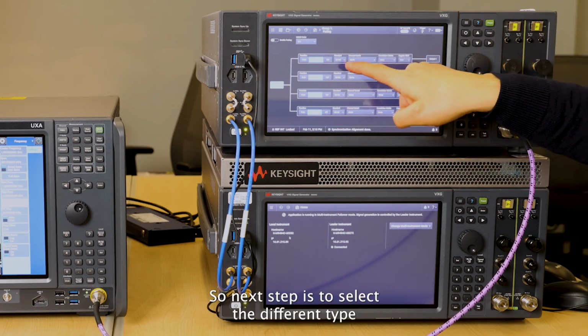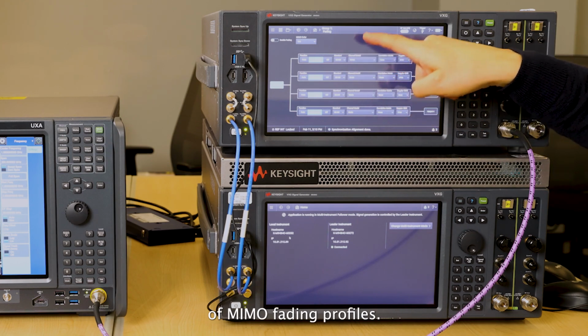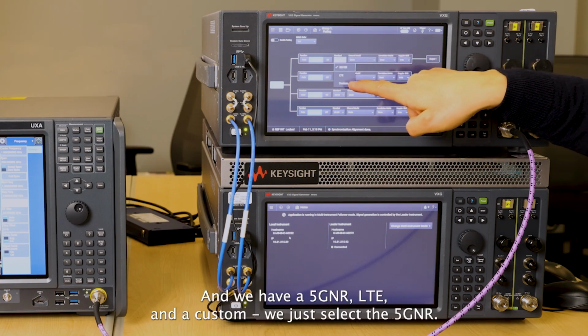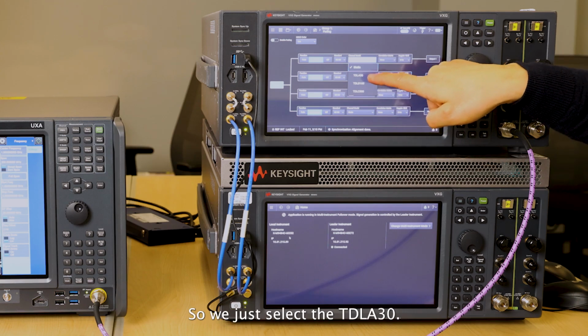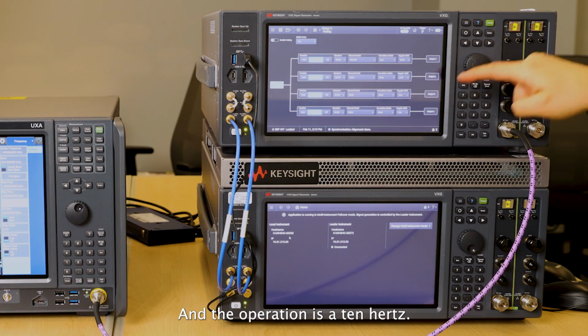So the next step is to select a different type of MIMO fading profile. Here there is a standard selection, and we have 5G NR, LTE, and custom. We just select the 5G NR, as this is the case. And then you select the channel model. So we just select the TDLA30, and the Doppler shift is 10 Hz.